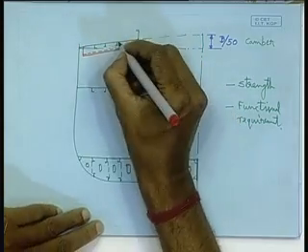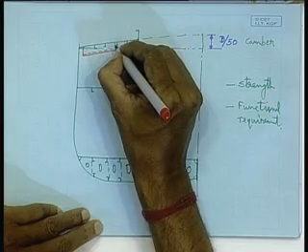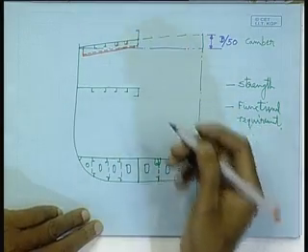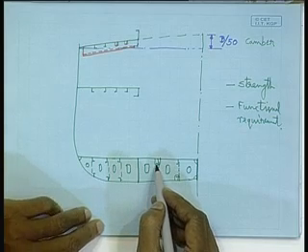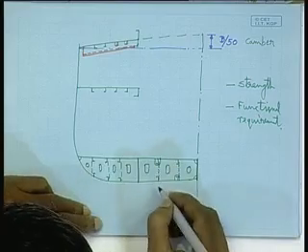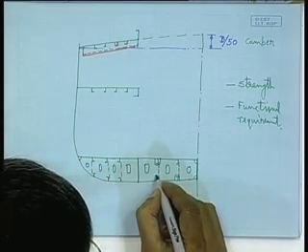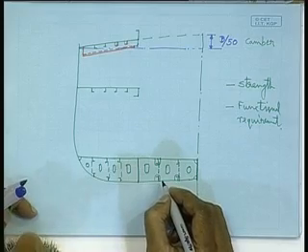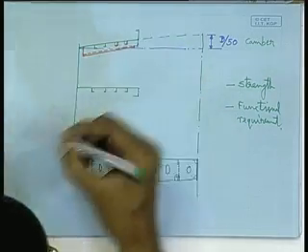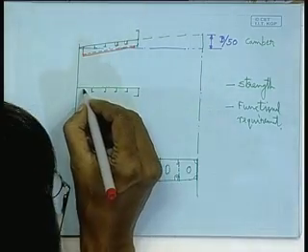Again the same thing here, you will have these so-called openings, like in the floor you had the same connections. Here the intersection of the inner bottom longitudinal and the floor plate, or the intersection of the bottom longitudinal and the floor plate, whatever is the detail we have already discussed, will be the same here also, right. So they are supported. The same thing will be there for the lower deck also.